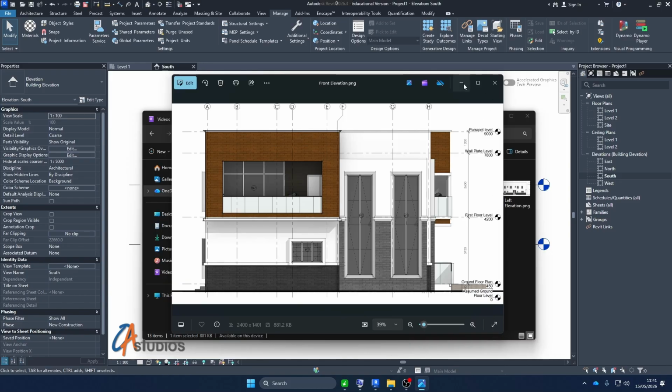Okay, so depending on the project you have, just make sure you determine these levels as you're starting up the project. They can change as the project or the design advances, but it's good to always have something in mind initially. So we'll just work with this. Assume ground level, ground floor, first floor, wall plates, parapet level, and then we'll use these dimensions to go with.